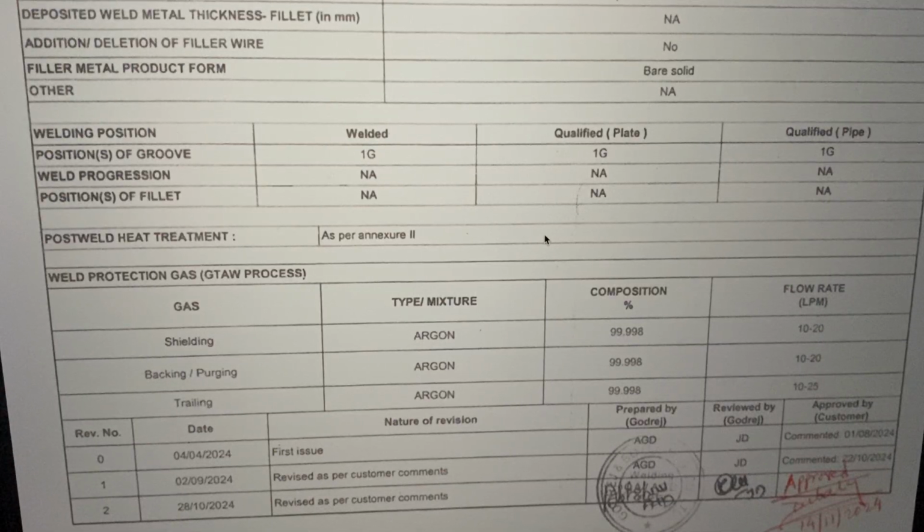And the post weld heat treatment, as we saw on the top, can be part of this: immediately after the welding, don't allow the weld to cool below interpass temperature or below your specified temperature, and heat it to that, so that the hydrogen gets mobility to move out of the weld, or if it has to accumulate, it can go and accumulate in any of the imperfections, non-conformances, and have a resultant impact, a crack or distortion immediately, so that we can take a corrective action rather than getting it suddenly after some days or some time has lapsed.